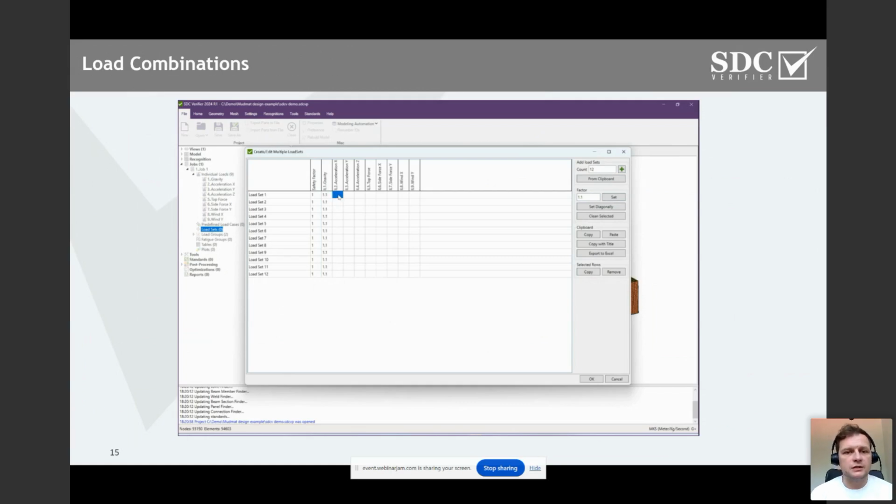While we have acceleration loads, you can define for your FEA analysis just one unit load of, let's say, 1 meter per square second, and then introduce the factors for the combinations to define different states. So it could be 3 base cases, acceleration in X, Y, and Z direction, but at the same time, the user is able to identify an unlimited amount of loading combinations within this load sets.